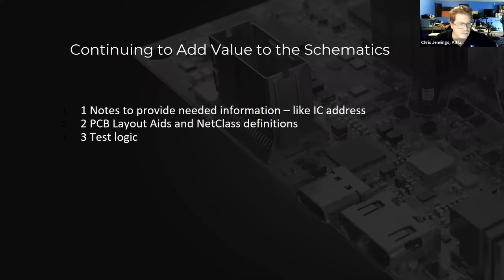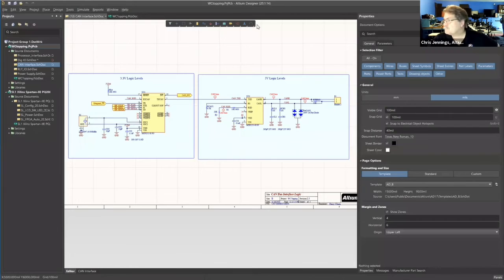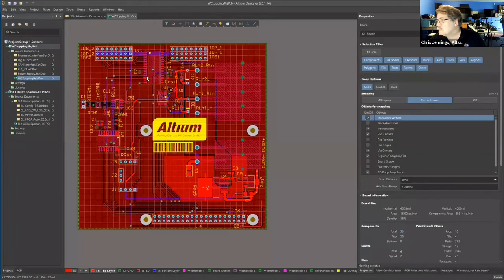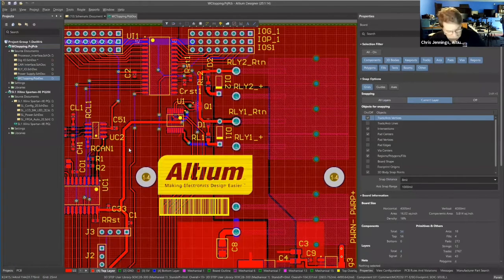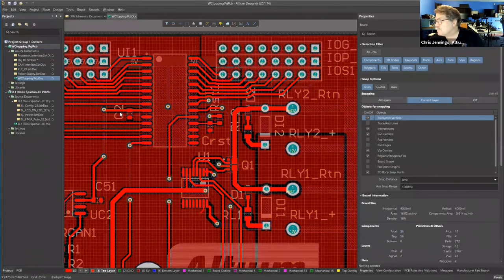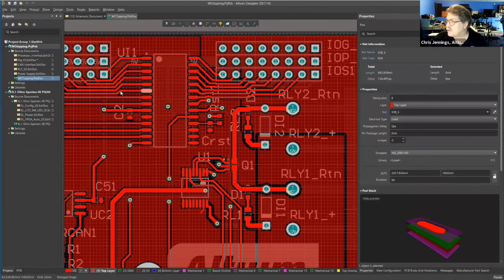I mean, it's kind of self-evident, but I've done things like, not necessarily in this design, but when you go into the PC board, you know, here, all of the signals are being used, right? All the pins are being used, but I've done things like if this pin was not used, but it was a free input or a free output, I might put a trace here and then drop a via in so I can connect up to that with wire later on in the lab and allow me to inject signals or test signals a lot more simply and quickly.